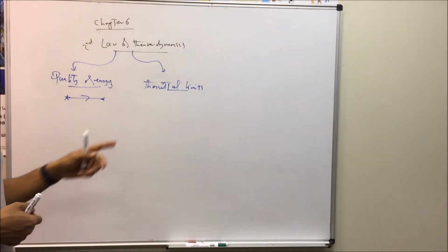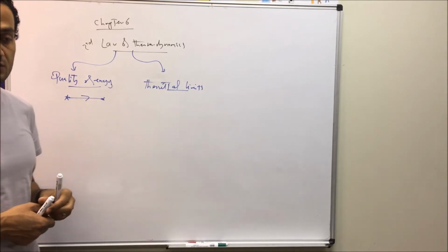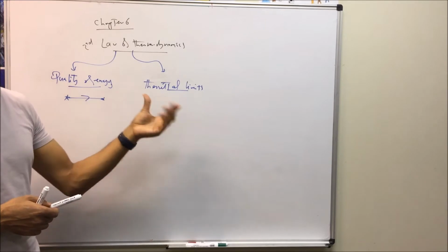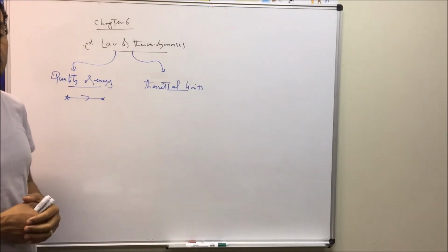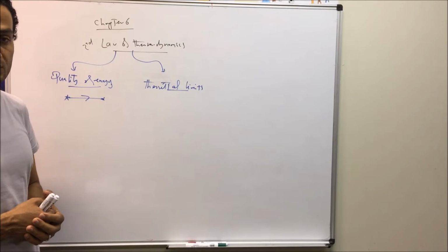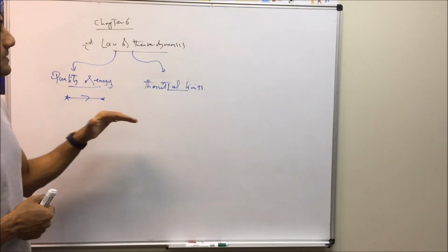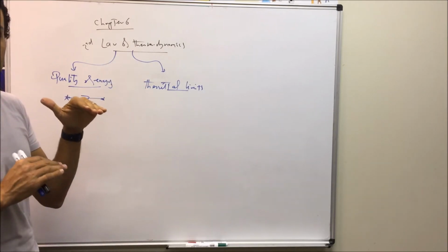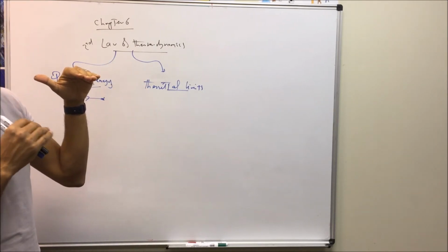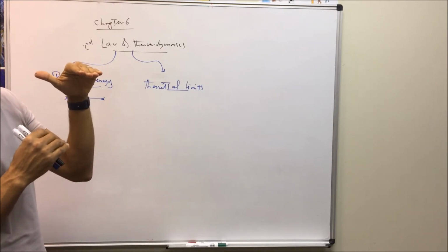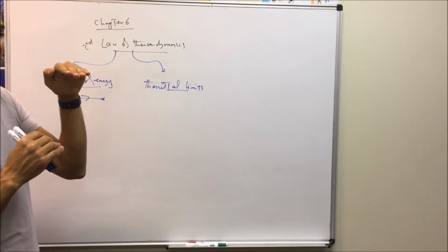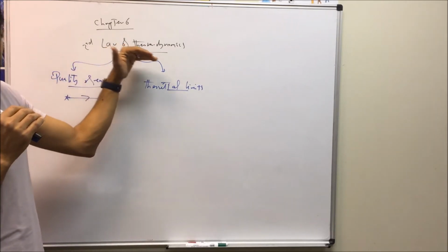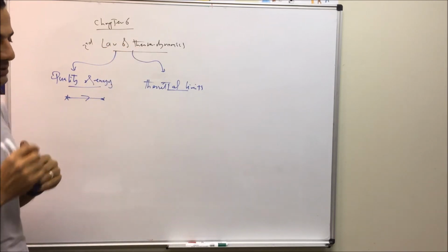Also, if you are getting a new device, like an air conditioning system or any other system, and it is written on the system or offered to you that it has a certain efficiency or coefficient of performance, then we can apply the second law of thermodynamics and calculate the maximum efficiency of this system. The actual value given to you should be less than the maximum calculated efficiency. If you have an offer with an efficiency greater than the limit, then this offer is not okay.